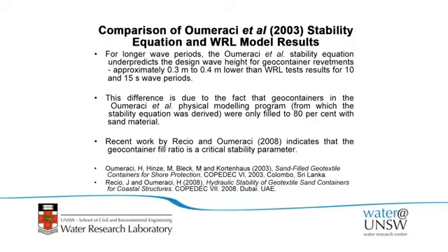We believe it's because their containers aren't filled properly. With the long wave periods, high energy waves, they tend to flop around and dislodge a bit easier. So at high wave periods, their criteria is lower wave heights, simply because of the fill ratio, as far as we can tell now. That said, we only tested a single fill ratio, which is 100%. They only tested a single fill ratio, which is 80%. But we believe that's the reason for the differences. So basically, their numbers generally underpredict what we came up with, and the reason is the fill ratio. They indicated it is quite a critical parameter.